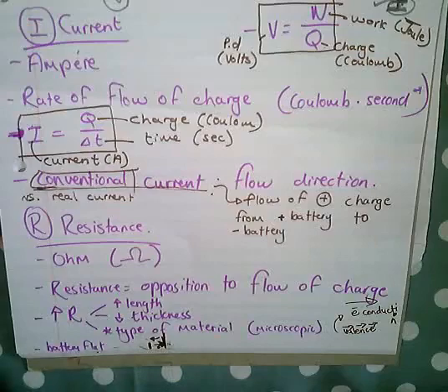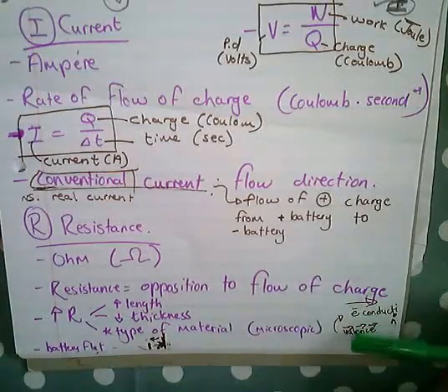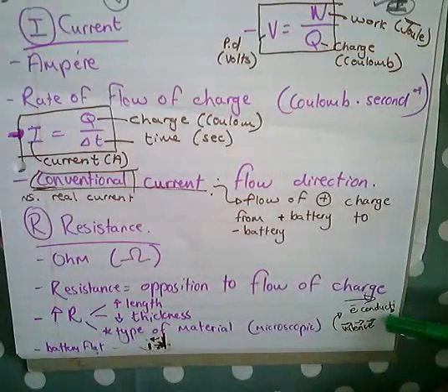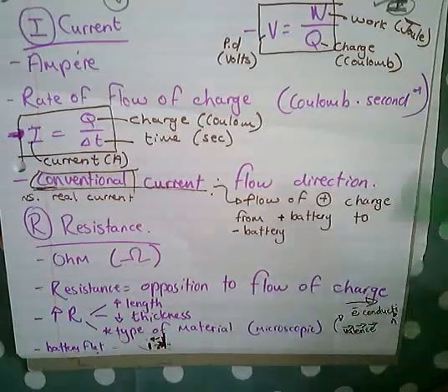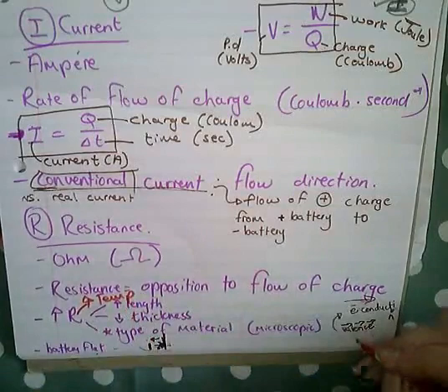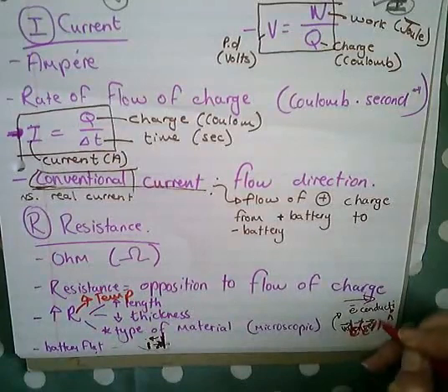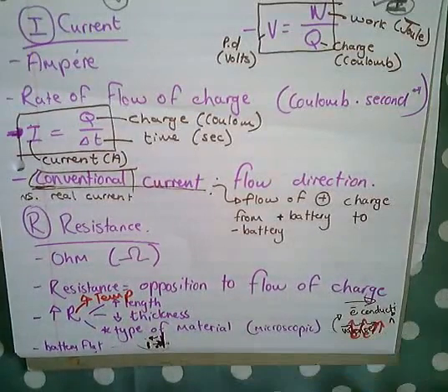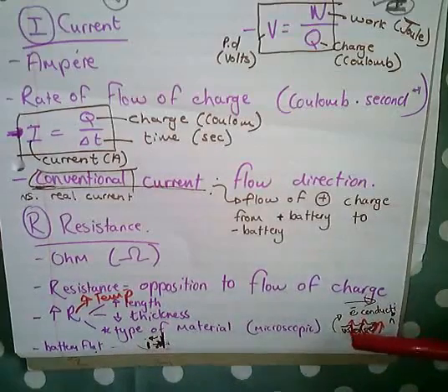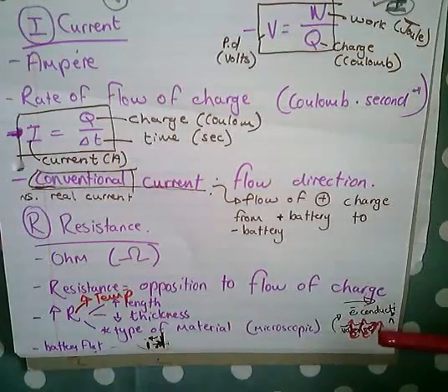Maybe I should just add here that the problem here is actually that the electrons jump because of the heat. So you know that the higher the temperature, another thing here is we increase the temperature. So the higher the heat, the more these electrons out of the valence band jump basically in front of or in the way of the electrons in the conduction band. So actually, if it has a conduction band close to the valence band and it's at a low temperature, it has a lower resistance and it conducts electricity easier.